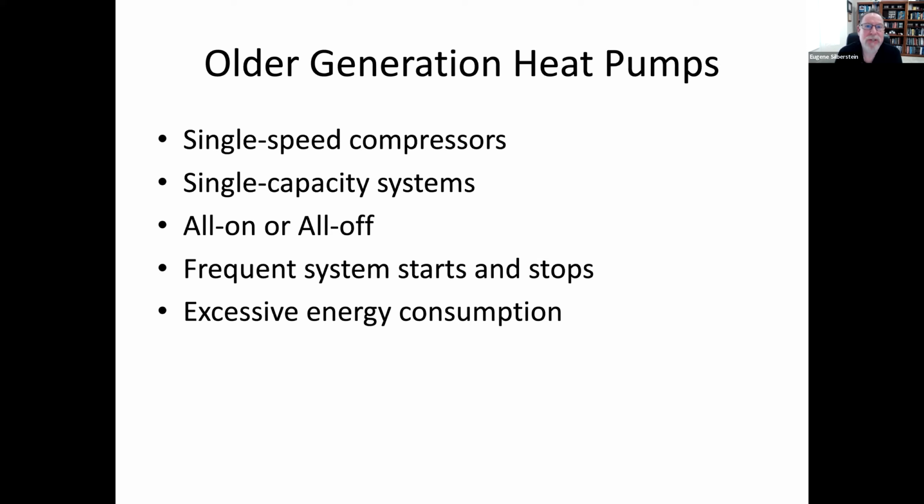Energy consumption was a big deal because we had our end users who weren't used to heat pump systems and how they actually function. And to alleviate a lot of the nuisance service calls that our contractors were getting, they were inadvertently, of course, tying second stage heat, our electric supplemental heat, onto first stage.